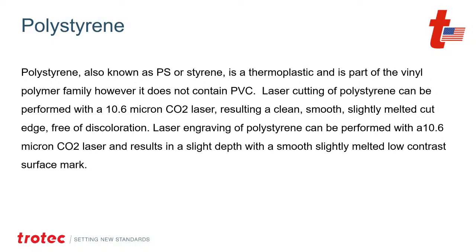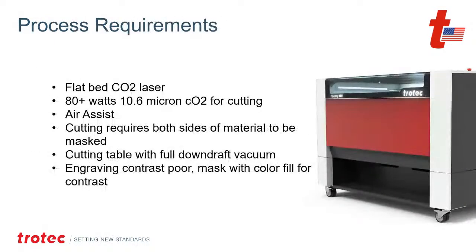Fiber laser does not work with polystyrene. Nothing's going to happen when the fiber laser works with it. So a Galvo fiber or a flatbed fiber laser is not polystyrene friendly. So we're not going to get into any of that, because it just does nothing. You can hit it with a fiber laser all day long, nothing happens. So it is a material primarily used with the 10.6 or the CO2 spectrum wavelength as the most common wavelength to respond to this material.